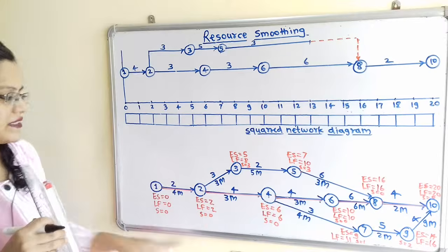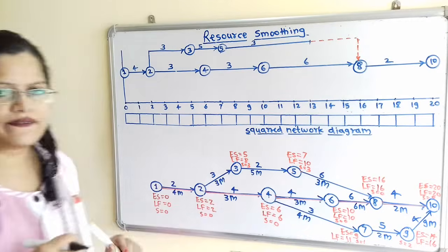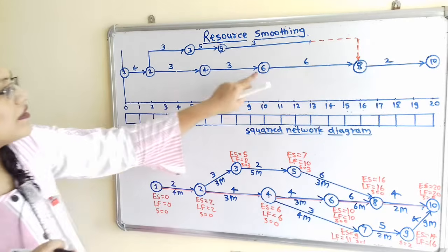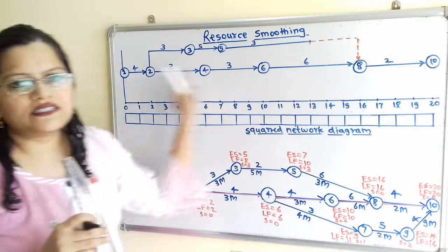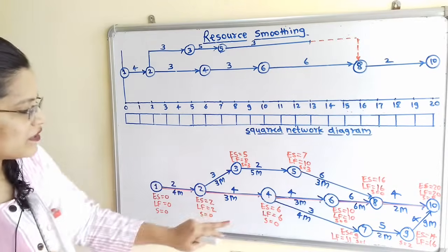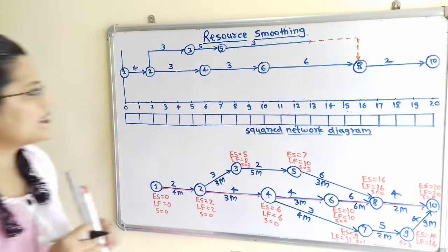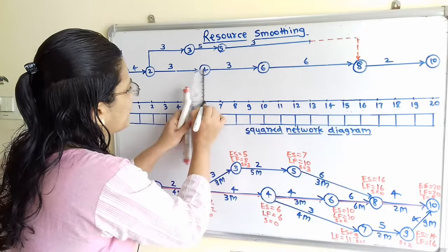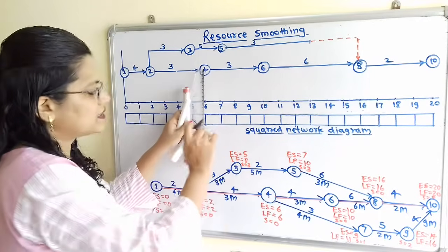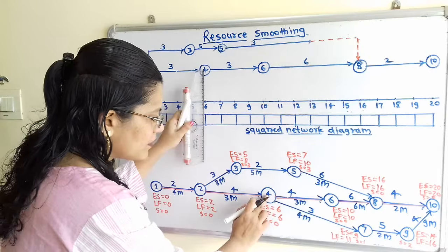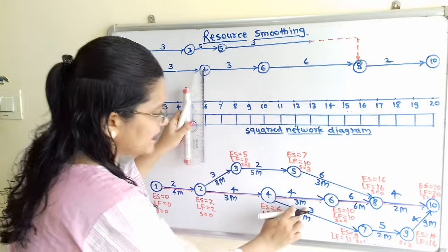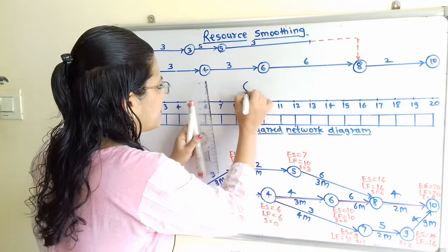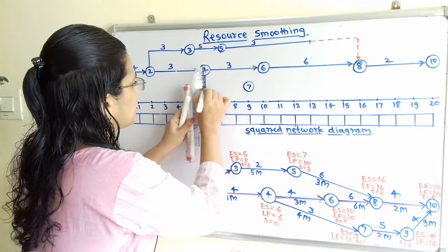Now we will move next, that is from 4 to 7. So how to complete this? So here is the node 4. Now 7 node is not contained in this critical path. So we have to mention here. So for this 4 to 7, 3 weeks are there. So the 4 node is present for the 6th week. So 6 plus 3, that is 9. So here we have to show the node number 7. Now we will complete this with this square.